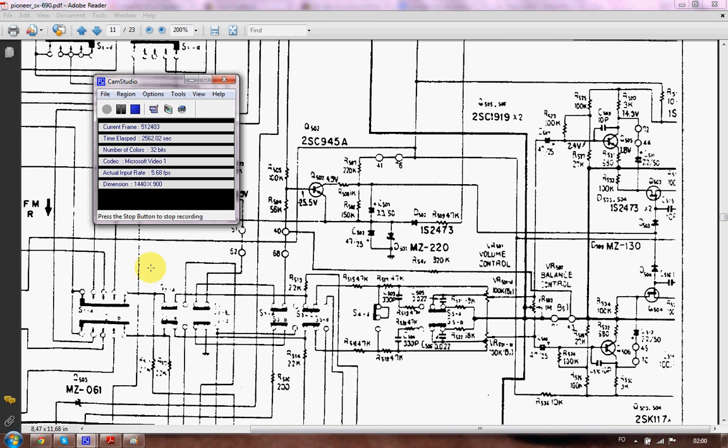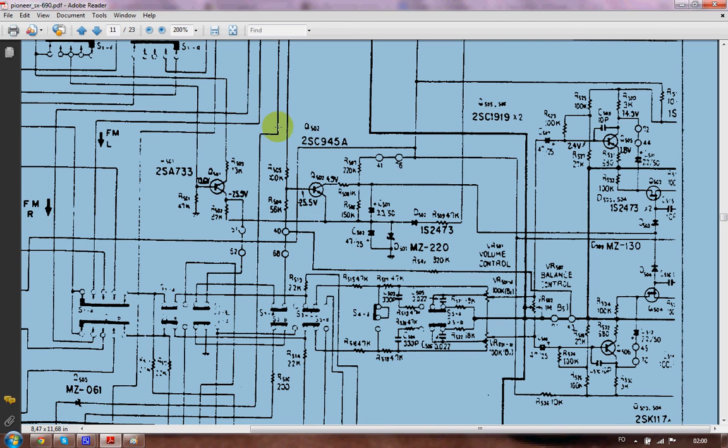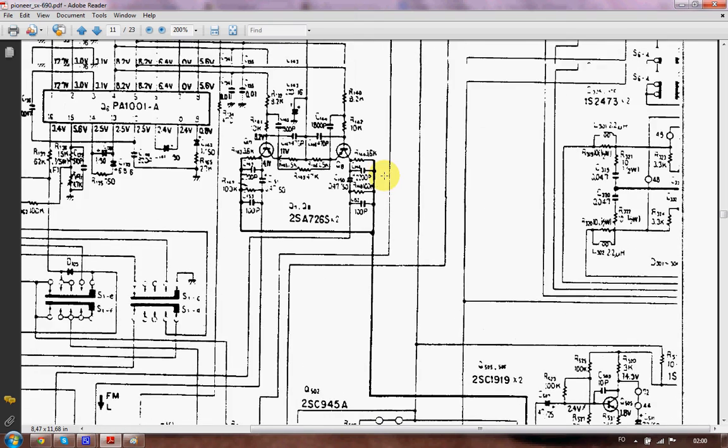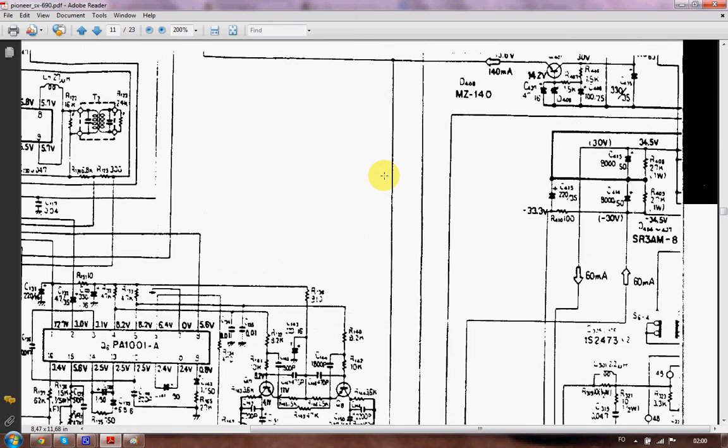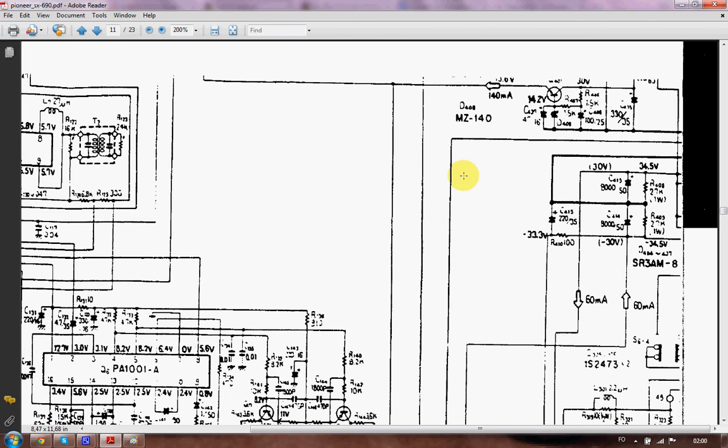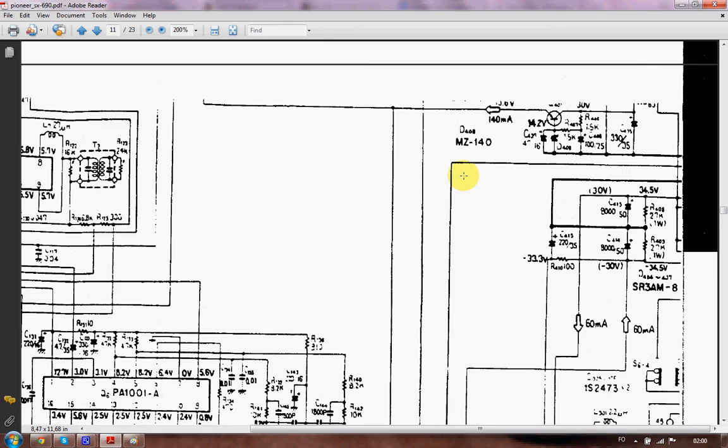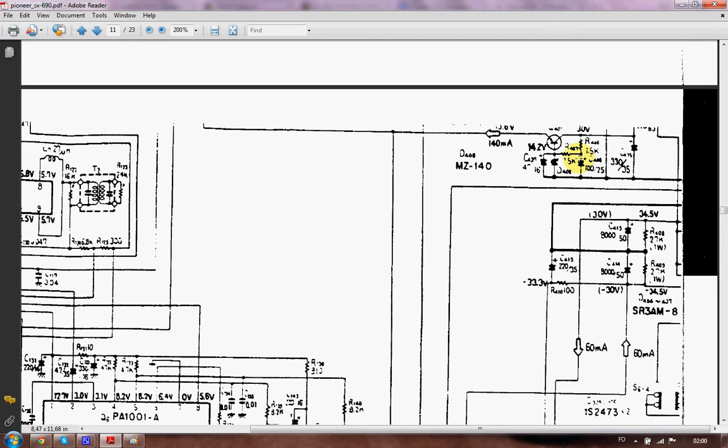I had a problem with this particular amplifier of mine, where there was no sound whatsoever. The main relay clicked, there was direct current voltage going into the amplifier, but there was no signal coming out of the amplifier, and I was lacking a lot of signals, bass signals. It turned out that this transistor here has failed, the uppermost one you can see.